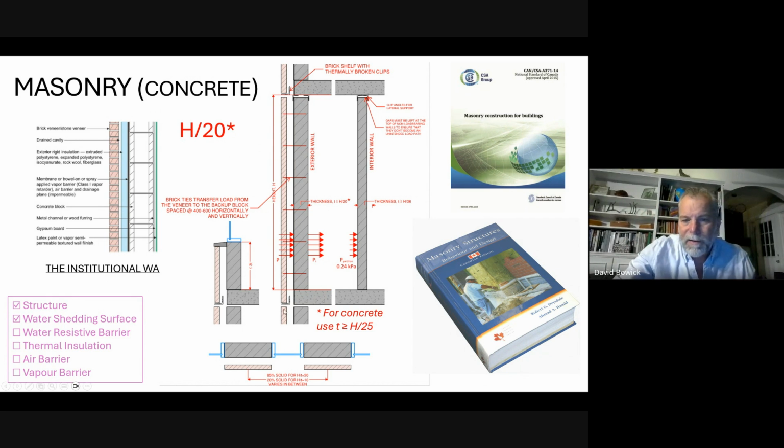You can see the masonry veneer at the bottom is supported on a shelf angle that is suspended off the structure. It'll be connected back to a beam or something. And look at this, we've got a little gap at the top of that masonry veneer. That has two functions. One is it allows some degree of pressure equalization. The brick veneer will have weep holes at the bottom to drain the cavity, and it has a gap at the top, which allows air in and out.